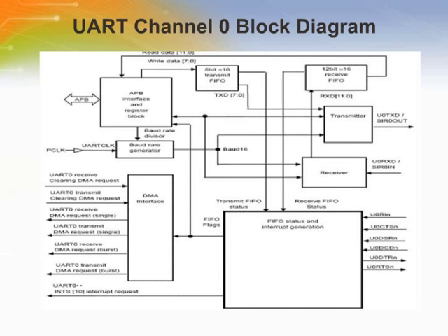A baud rate generator. The baud rate generator contains the internal baud 16 clock circuit, which controls the timing of the UART transmit and receive, and the internal IrLP baud 16 circuit, which generates the pulse width of the IrDA encode transmit bit stream when in the low power mode.